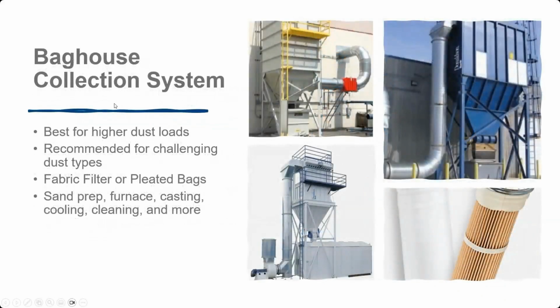And then the other type of collector is the baghouse or pulse jet dust collector. The pulse jet dust collector cleans during operation, and that was the main reason it was invented, I think back in the 50s or 60s maybe, because before they used shaker style dust collectors where they would have to shut off the operation and shake the dust off the filters.